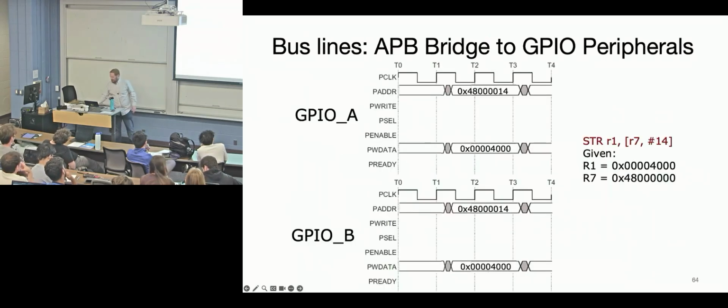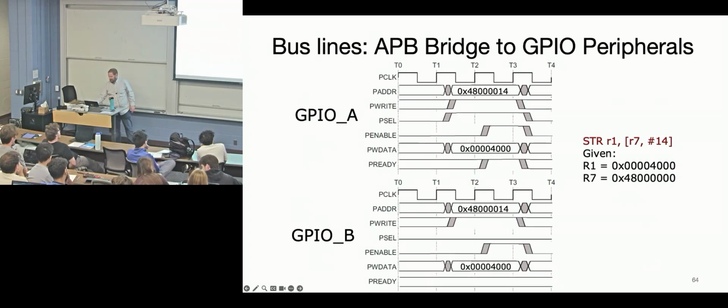Do we know how many cycles after, for the bus control signals that some of these are triggered? So go back, right? So p-enable goes after two write cycles, 2 clock cycles. Is it always that case? P-enable, there's a setup phase. And this bus architecture says that these things must be instantiated, not the clock, but these things must be instantiated beforehand, so that you don't want things wiggling around when you're trying to do an action. So it says there's a setup phase and there's an action phase. So yes, there must be at least 1 clock cycle between setup phase and enable going high.